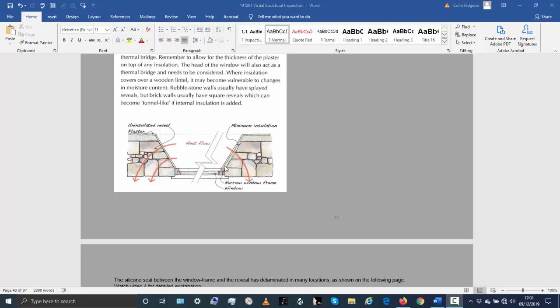There are some solutions, so I'm going to suggest you look up a very compact form of insulation called a vacuum insulated panel, or VIP. Some people will put vacuum insulated panels around window frames. It's not that commonplace yet, but it's becoming more popular on the market and may help remediate that problem in the long term.